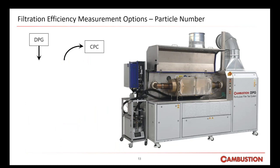So, filtration efficiency measurement options based on particle number. The PN basis filtration efficiency measurement uses the Cambustion dual diluter, which incorporates a TSI 3790 engine exhaust CPC. This has a 23 nanometer cut. The dual diluter has separate diluters for upstream and downstream concentration measurement. In the box there, this addition on the side of the DPG is the entire diluter and CPC instrument.